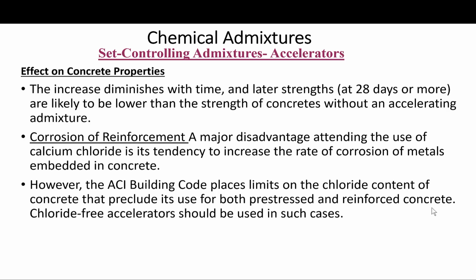So with the chloride, as I mentioned here, the ACI building code does not say do not use calcium chloride. But in the code, there are limits on the total amount of chlorides that can be present in a mix, which are different for conventional concrete and pre-stressed concrete, being much lower for pre-stressed concrete.